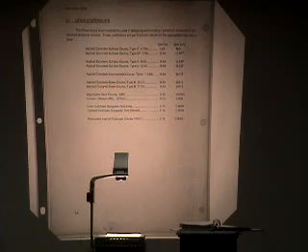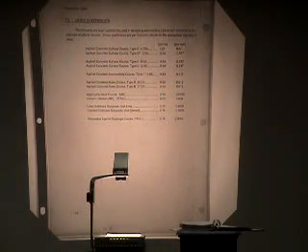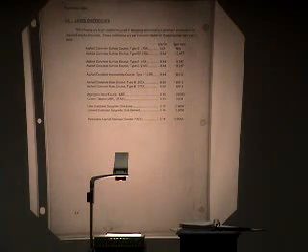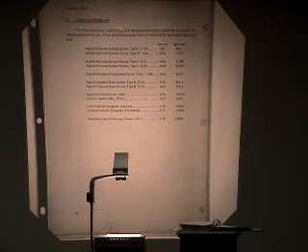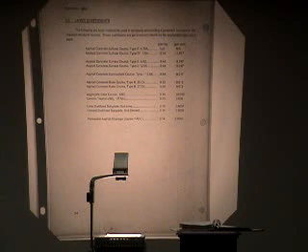And then when you get down to asphalt base mixes, rather than 0.44, that number is 0.30. Again, these are just relative numbers. So what that's saying is 0.30 is about 2/3 of 0.44. What that's saying is that on a per inch basis, base mix is about 2/3 as strong as intermediate or surface.